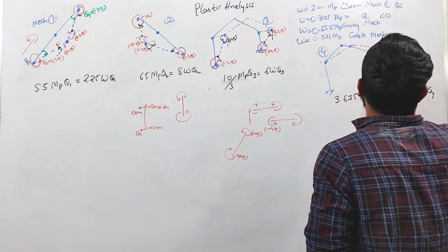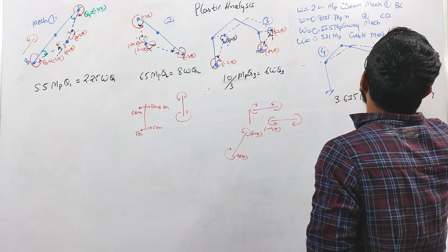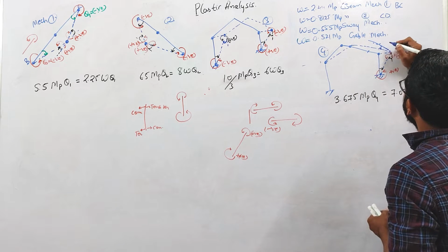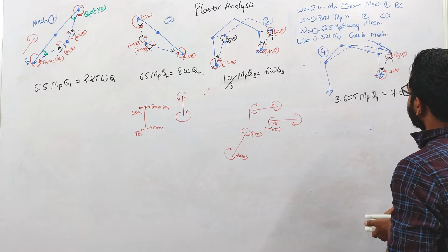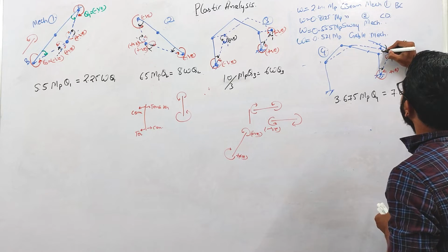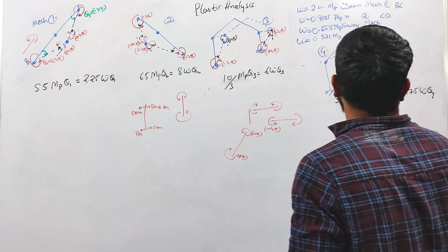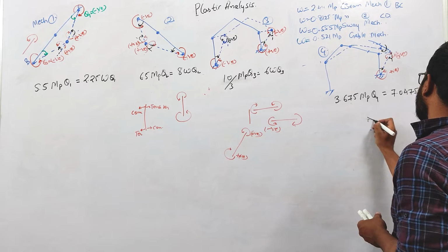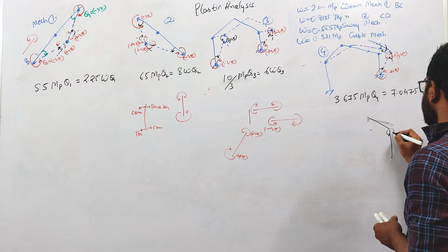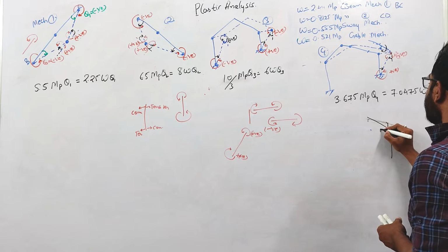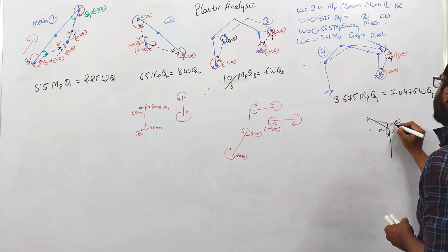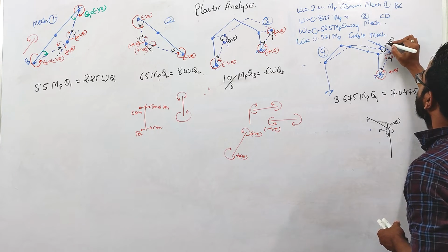And here, suppose these two lines are parallel. So here the direction of the rotation is what? Again clockwise. So to balance it, the moment will be anti-clockwise here, and clockwise there. Okay. So this situation is like this. This is anti-clockwise moment, and here this is clockwise moment. So both moments are producing compression inside. So both the theta will be considered negative here and negative here. Okay.